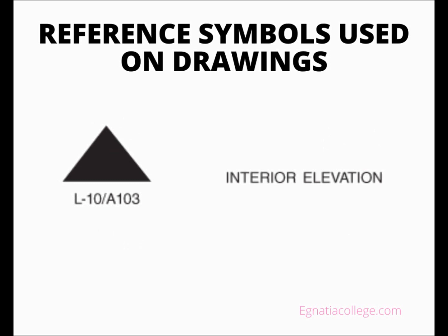An example from the drawings that are used with this textbook can be seen on the first floor plan, sheet A101. At the extreme right and left ends of the floor plan there is a section view symbol, with its pointers directed toward the top of the drawing, north, according to the symbol in the lower right corner of the drawing. This symbol refers to section view J14 on sheet A201. Section J14 is in the top right of sheet A201 and is a full cross-section view of the building as seen by a person standing on the south side of the building and looking north.